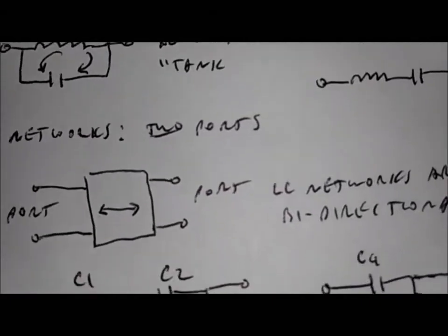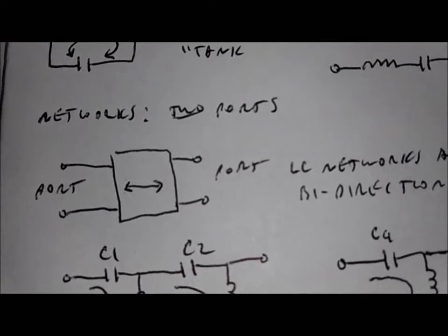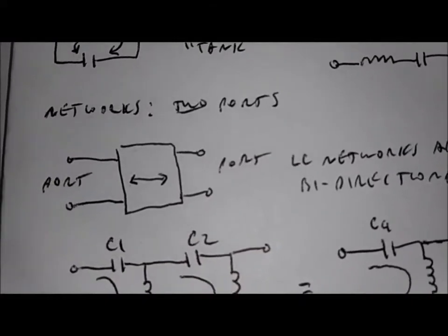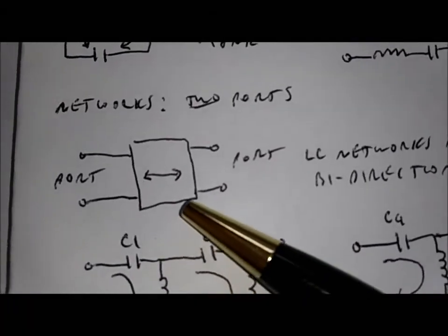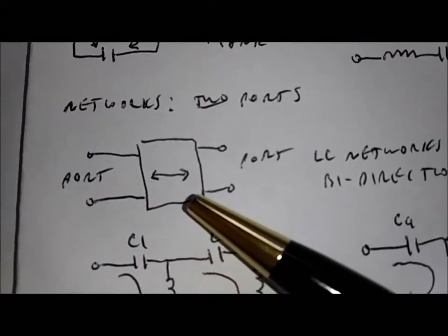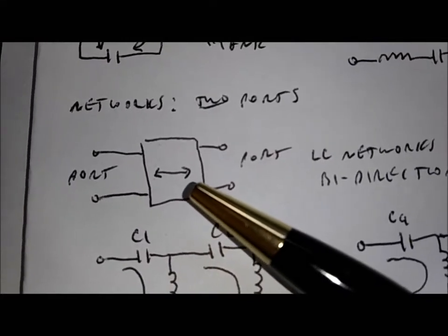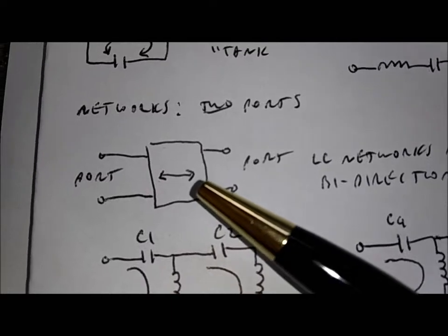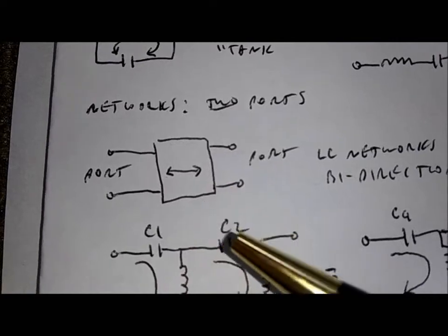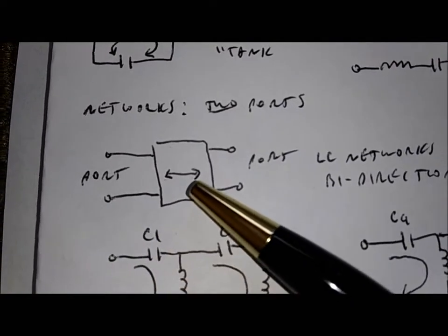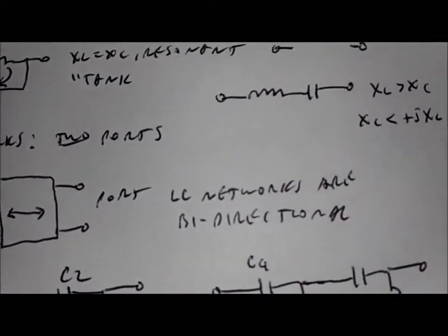Okay, networks are made of those components, generally analyzed without resistance. We buy good components, we minimize resistance, which is mostly loss. A network can be approximated as a black box with a port on each side, and very important to notice, they are bi-directional. So this baloney about magic tuners making all the reflected power from the antenna go back to the antenna is flat out BS. Networks do not have that magic property, and I mentioned that in the expose on tuners.